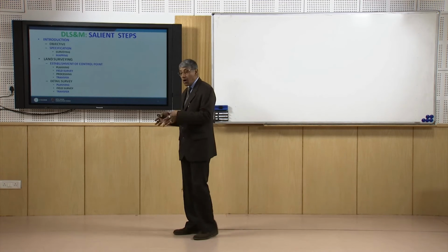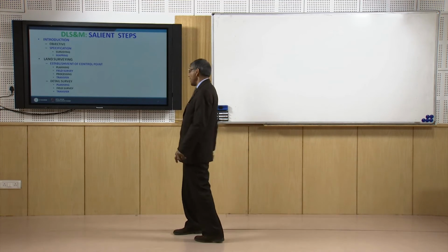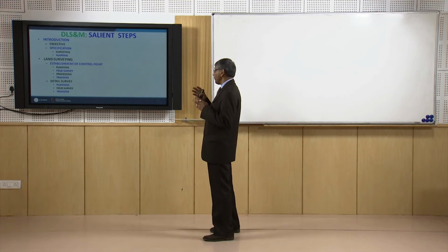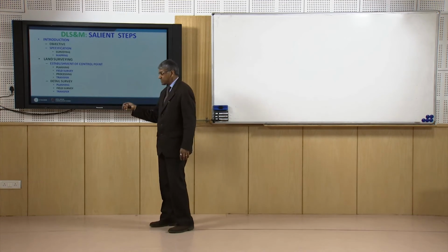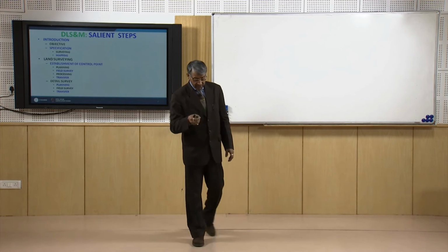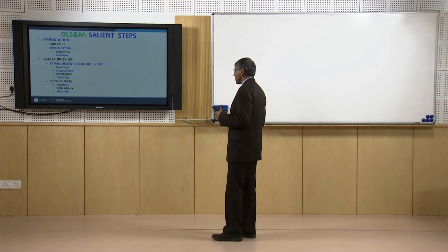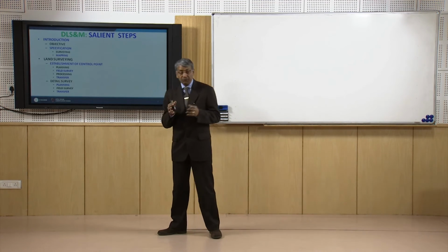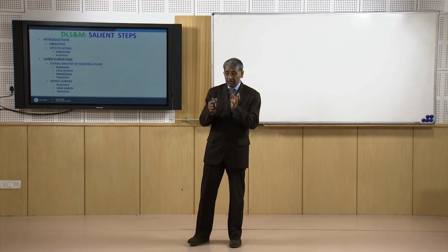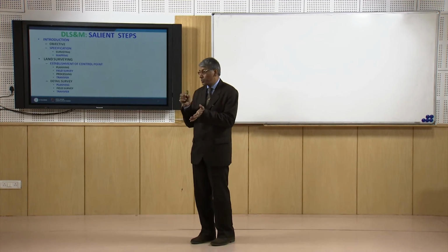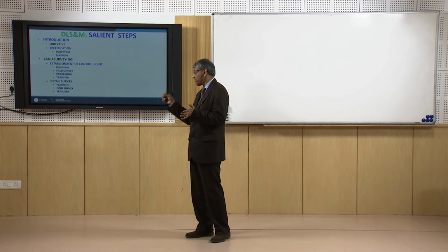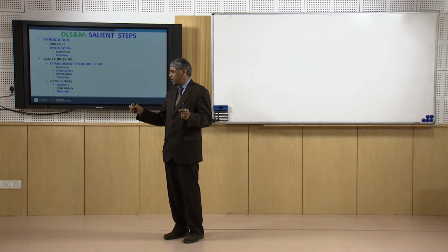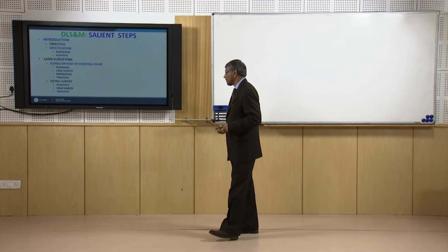establish the location of the total station, and subsequently those different points or objects have to be collected or noted down. The location of the objects has to be noted down along with their defined features. That means if there is a tree, we will not only locate the coordinate of the tree, but also note down along with that it is a tree, or corner of the building, or lamp post, or corner of the road. All these things we have to note down during field survey.